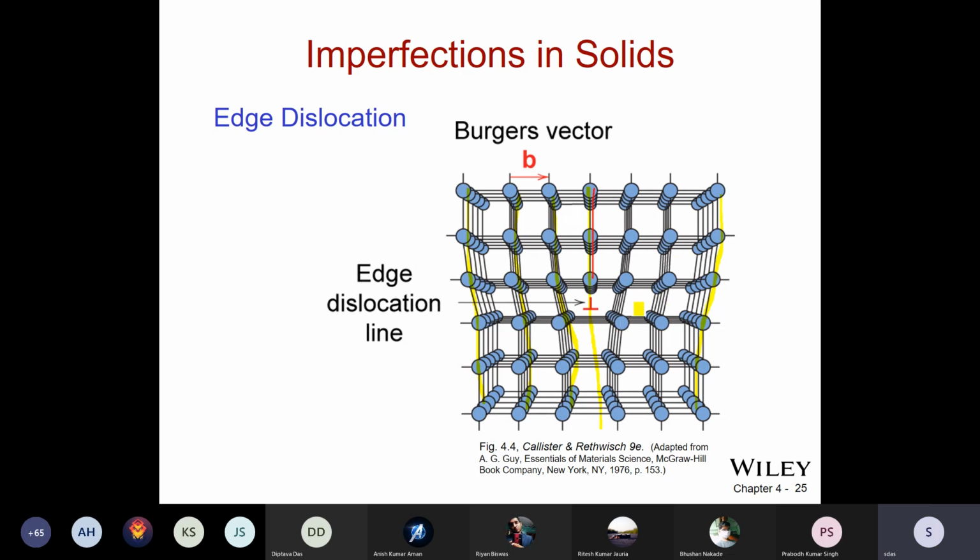You see by schematic diagram. The lattice got distorted from its equilibrium position. And the dislocation where there is an extra half plane, that type of dislocation is called an edge dislocation. If you look from the top, it appears like the edge of a knife. So the name edge dislocation came. I shall continue this portion from the next class. Any question?